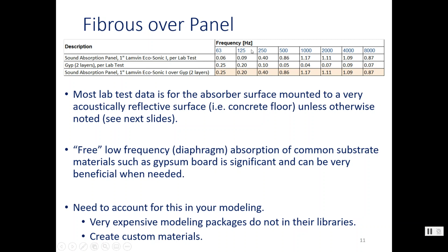Now, say you were doing an acoustical model of some space, and you make some measurements, or you model this room, and you see that you have too much reverberation. So say you're seeing too much reverberation up here, the mids and highs. So you say, okay, I need to put in some sound absorption panels, and you say you have to put in some 1,000 square feet, something significant like that.